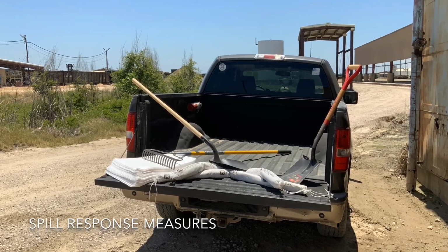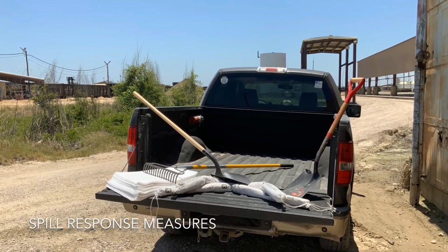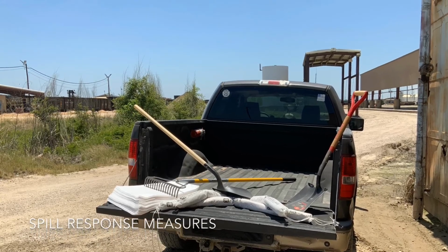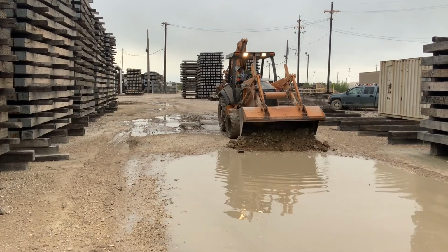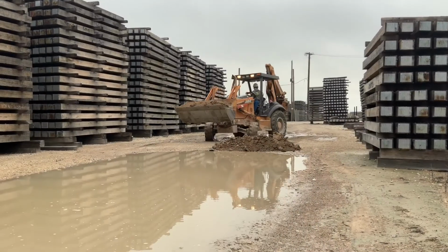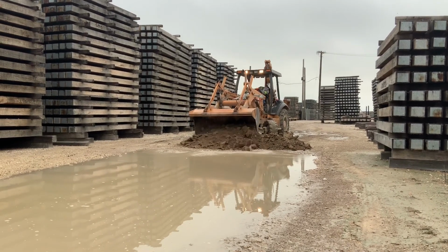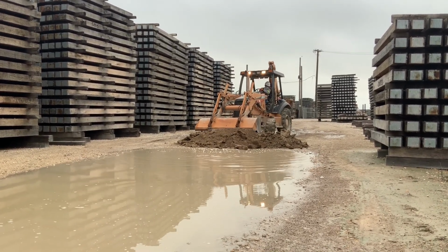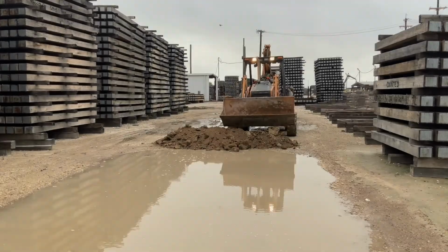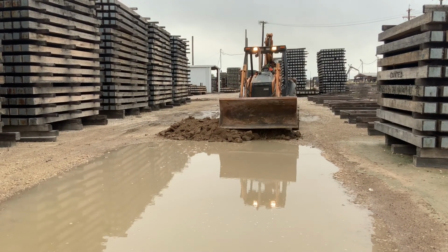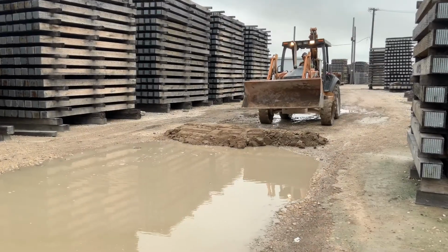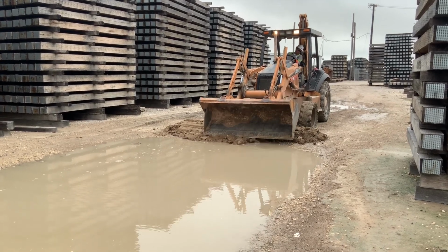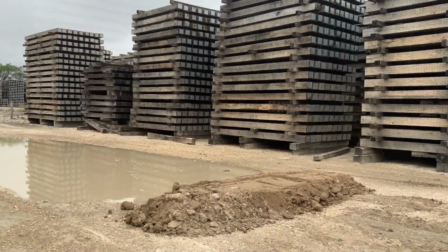Spills have the potential to contaminate stormwater if they are not properly cleaned up. Spill response and cleanup can be accomplished in a number of ways. Vehicles and mobile equipment can be used to transport tools and spill kits. Pumps can be used to transfer liquid into containers, and oil-absorbent socks and diapers can be used to collect or contain spilled material. Mobile equipment can be used to construct soil containment dams and remove contaminated soil. After spill response and cleanup are completed, equipment should be decontaminated inside containment before being released back into the plant.